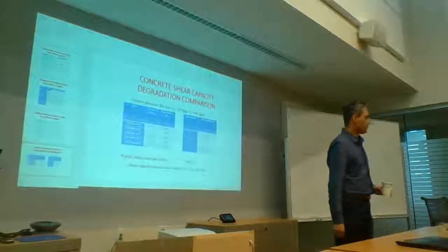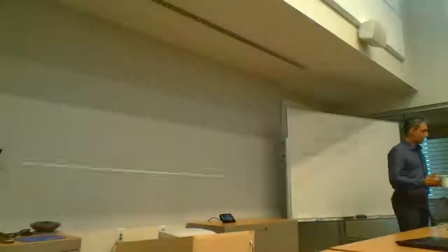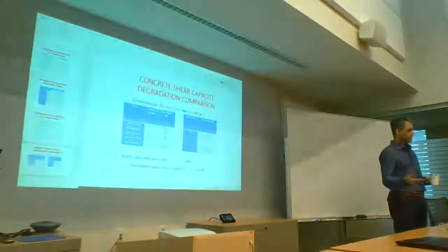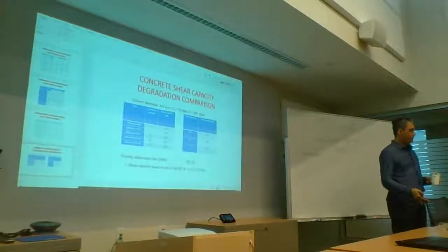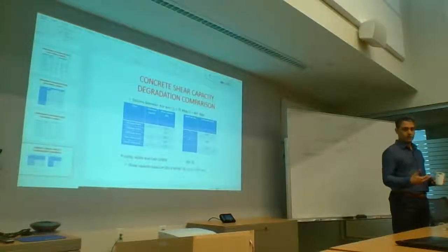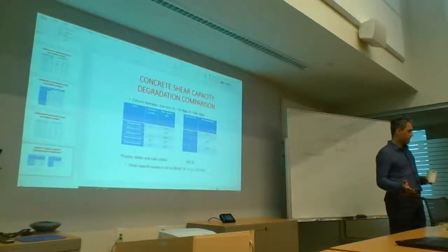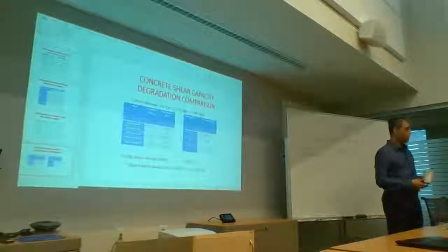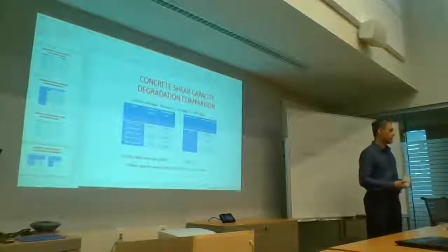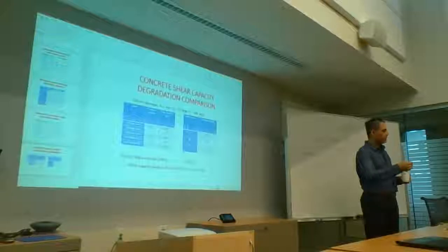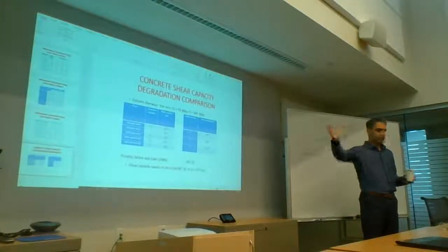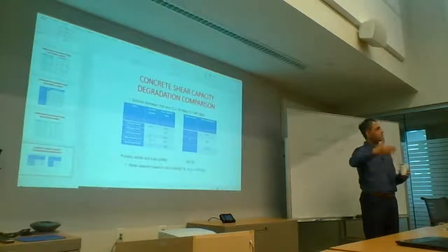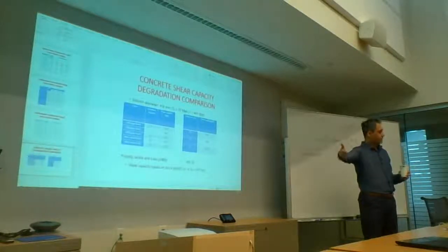Did you put 5.1%? No, that's not it. This was designed beforehand, and then the code changed. So this was a study done to see, if we use the current code stipulations, where would we end up? Our thought was that we would end up with a very impractical rebar ratio, and we actually did. So it just proved our worry that not having a rebar yield at 475 is very impractical. The other 2 criteria just hold in because their strain limits are quite relaxed.